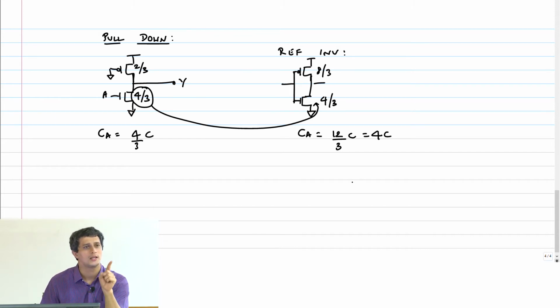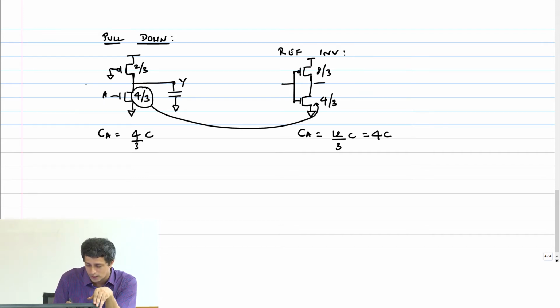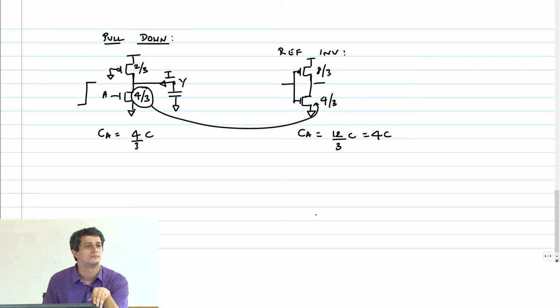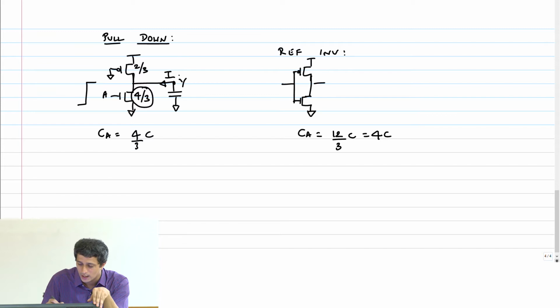So here in the pseudo NMOS case, what matters is this current. So input is going instantaneously high. Therefore, we know that the current coming out of this load capacitor should be I. So what you should do is not this, but instead take this I and put the number here.